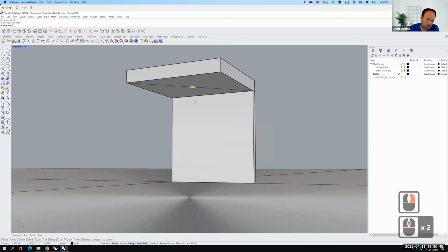And remember that the V-Ray light has to be created in the final scene. If you're working on your retreat file and you put all of these blocks into your retreat base file, that's great. But the actual V-Ray lights have to be in the master site file. It's just one of the quirks. So we're going to create a V-Ray light that mimics what's happening from this light here. And we're going to do that using what's called a spotlight. It's the closest thing to this style light that we have. So I'm going to go ahead and click on spotlight here.